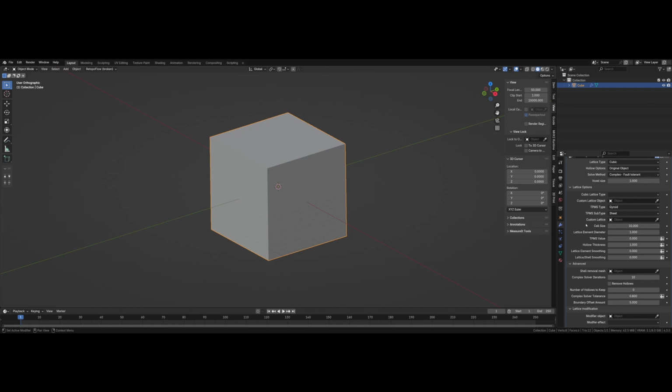The part I'm working with is a simple cube 100 units on the side. Let's say I want to make a 2mm thick hollow with a primitive cubic lattice inside it. So it's best to set the values now and then activate it by changing the hollow option. Otherwise it will want to do the whole calculation process with each option change.